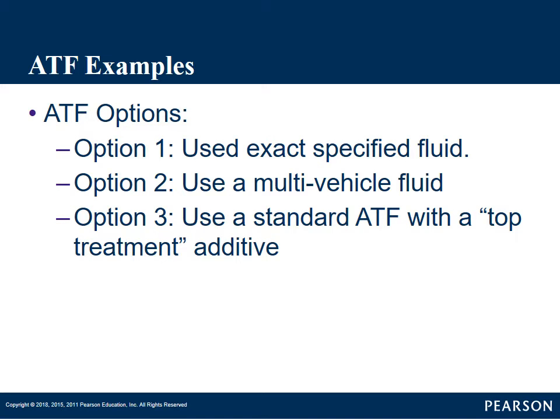ones it won't. A lot of times you can get a chart if, say, you're using a Peak multi-vehicle transmission fluid. You can usually get a chart from Peak to say what fluids this will replace and what fluids it will not replace. Because rarely will a multi-vehicle fluid cover absolutely every single transmission fluid. Usually there's some that it won't. Okay, this is the most common method that most independent shops use.